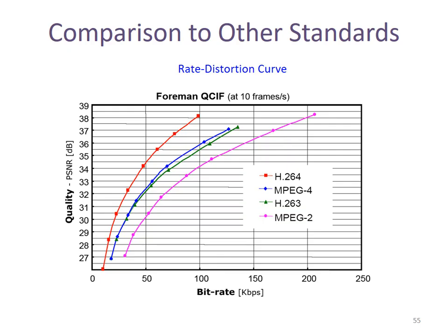If you want to preserve better quality, intuitively, if you assign more bits, then the quality will be better. But we want to achieve higher coding efficiency. We want the bit rate to be as small as possible. But once the bit rate is too small, it can damage the quality of the videos. So we need a balance between these two indicators.